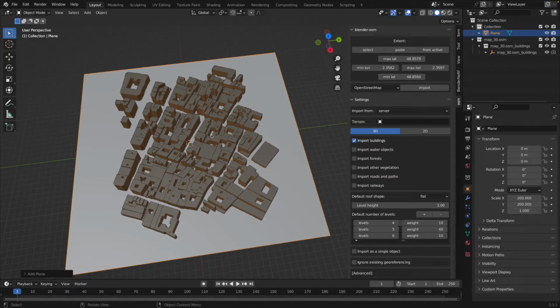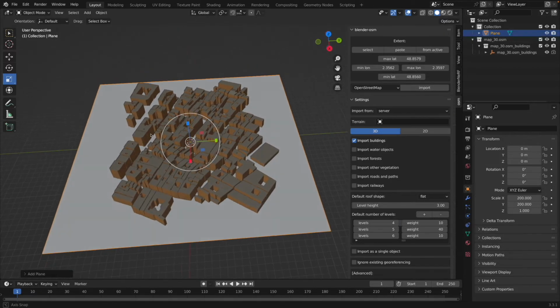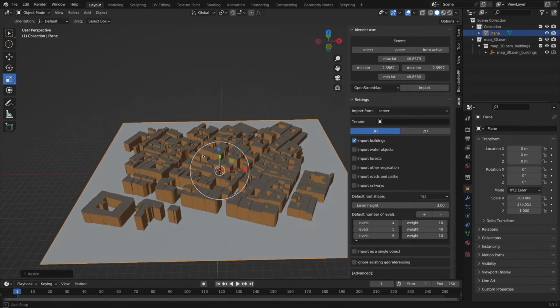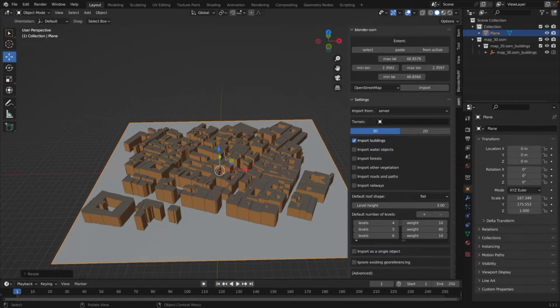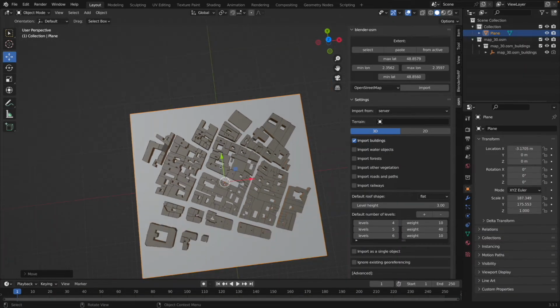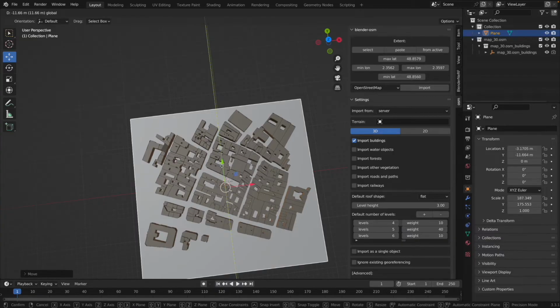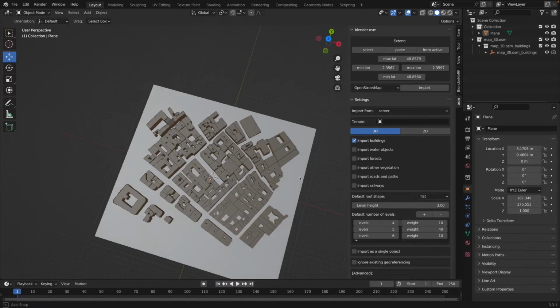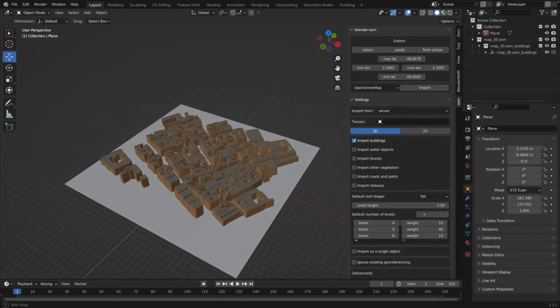So we can precisely adjust the scaling of the objects by selecting the scale tool here. When clicking on scale, it opens this small frame that we can use to precisely adjust the scaling of the objects along the 3 axes, X, Y, and Z. We can also translate the object by selecting the move tool here and then translate it, for example, to center it on the scene we have imported. Okay. Once this is done, the geometry of our scene is set.